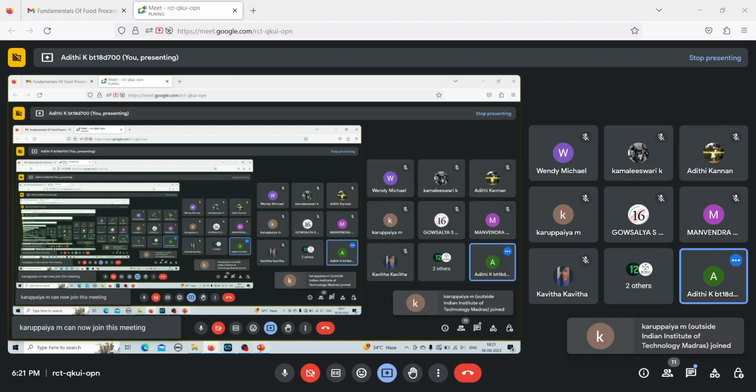So now I am using the energy balance and substituting whatever we know here. We don't know what S is here. We don't know how much steam we are letting in. That is not given in the question. So S into, we know the latent heat of vaporization of the steam, which is given as 2150 kilojoule per kg, and F is given as 132 kg per hour.